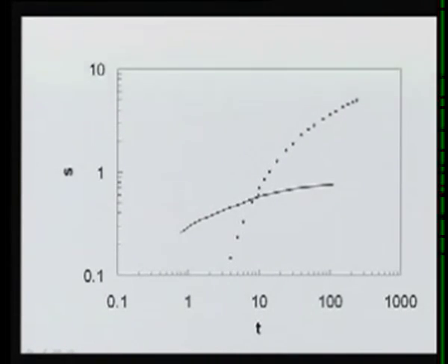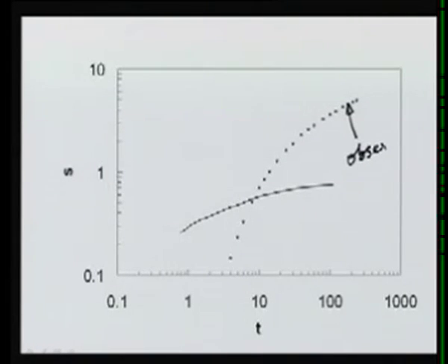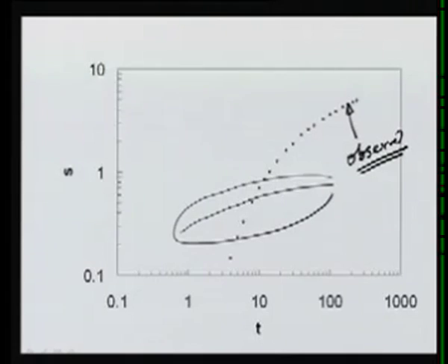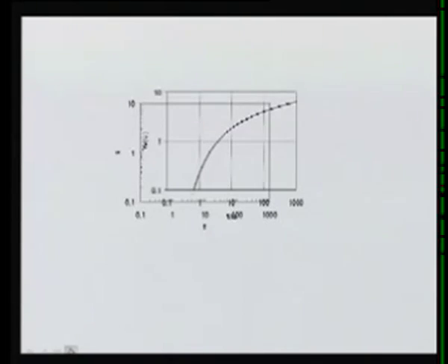So again we can use the Theis curve matching technique to match this observed drawdown curve with the type curve. And of course, in this case, the shifting will be different than the previous case where the curve was like this. So here you can see again that the data now plots in this portion. Again, a very good match is being observed. Now we can again obtain the same